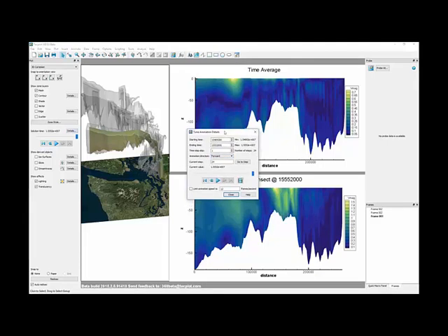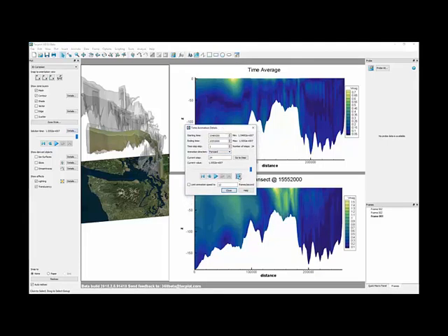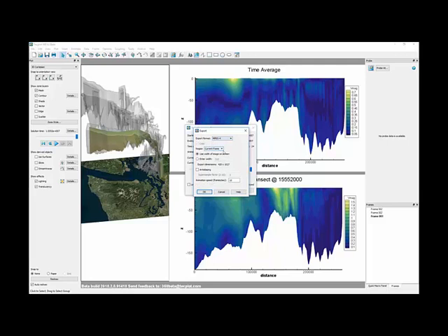Okay, so time animation details, we want to export to a movie, so we'll just click on this film strip icon, and let's go to an MP4. And the critical thing here is that we need to select the proper region. So the current frame will export just this one frame with the bold border around it, but we want to export all the frames. We'll specify a width. Let's go 1024.